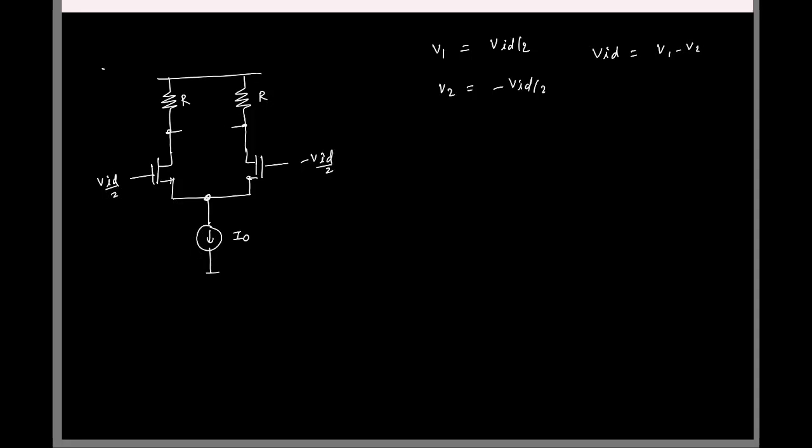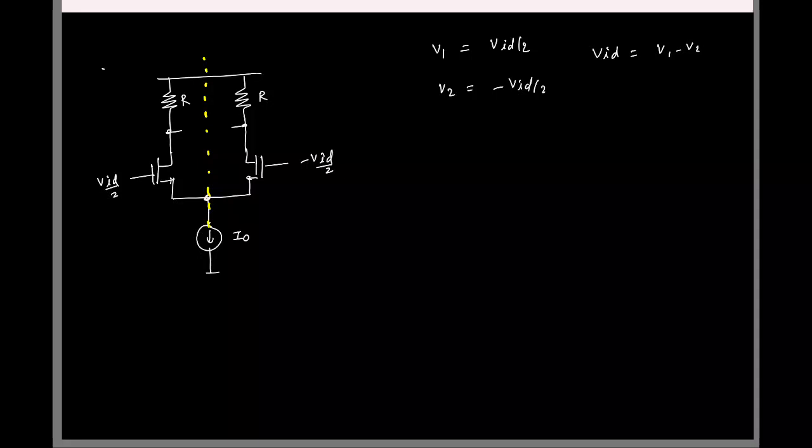Now if this is the case, can you do something to the circuit to simplify? We have already seen, right, all the nodes along this line of symmetry, what will be the potential, response signal potential? It will be 0. And by the way, do you think this is valid for any circuit, or is there something that needs to be satisfied here? What needs to be satisfied? No, there is nothing to do with the node impedance, right? Here we are looking only at symmetry.